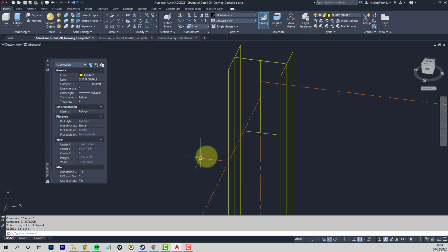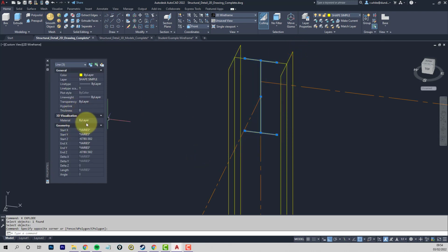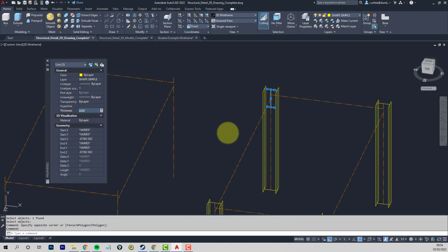And then, because this is kind of paper thin structure, the length of that line is 6,000. So we can use that with the change command. We could put in 6,000 at this point here, and it's going to come towards us. If we use minus 6,000, it will go back this way.